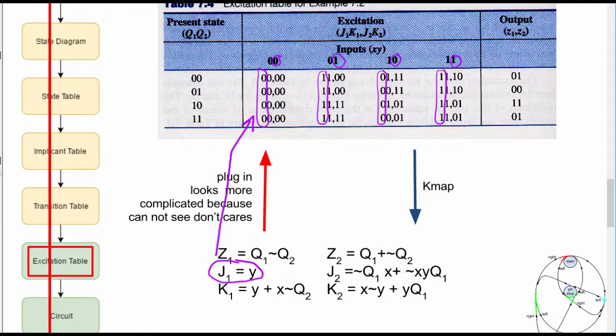But what about the other analysis, the design engineering analysis? What would it look like? How would we take this and use it to build a Karnaugh map? What would the Karnaugh map look like? Well, let's choose some output. Let's choose something complicated, J2. So where's J2? J2 is this column right here. So that's our output that we're interested in turning into a Karnaugh map.